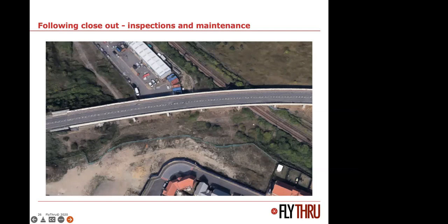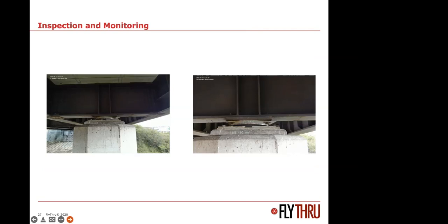And originally they were inspecting this using MEWPs, mobile platforms. It's impossible to do it now. So we now fly these by drone, man lifted over the fence with the drone and with an engineer. The types of images that they ask us to collect are the ones that are shown here. One is the wide normal image that we take. The other is the slightly more focused zoom, but we haven't over zoomed this. This is purely taken from a video, so it's taking simultaneously a wide angle, a more zoomed photograph, and also thermal at the same time.